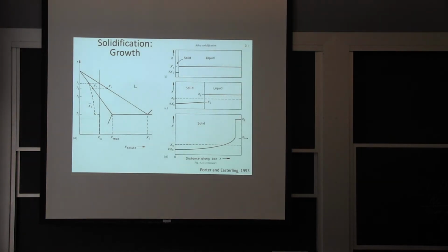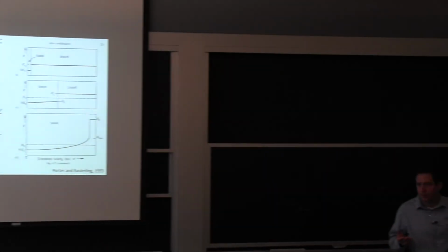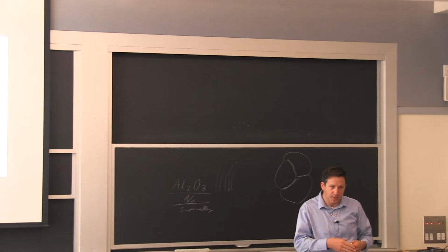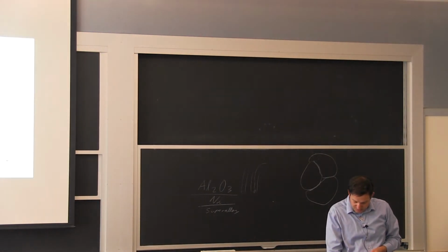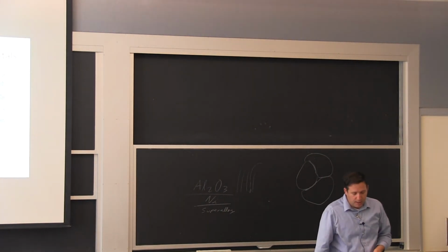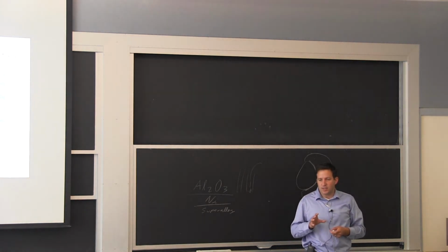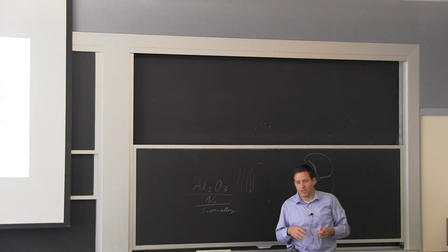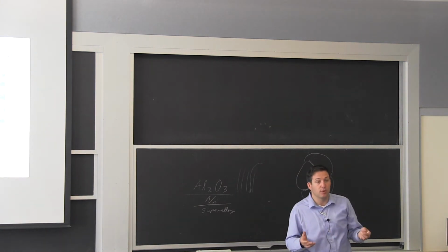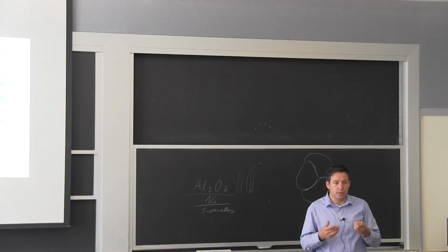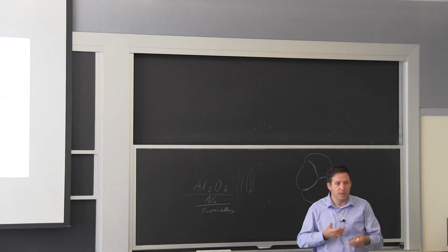That's why, especially for steel, we go through deformation processing, because as cast, we get a structure that is different from the edge to the core, and it has all these big grains that are visible. In deformation processing, one key concept that I try to convey is that if I go to high temperature and the steel is hot and I keep deforming it, I get this dislocation structure on the inside that stays the same. So it's becoming kind of a viscous material that I can keep deforming and keep deforming.